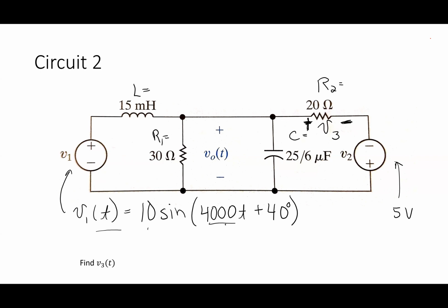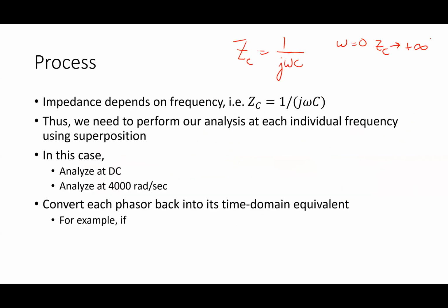If I had a second order circuit and I was worried about the transient response and I had only DC sources, you always say in steady state, what does the capacitor look like and what does an inductor look like? So when you had DC circuits, you said a capacitor in steady state is a what? An open. You said an inductor in steady state is a short.